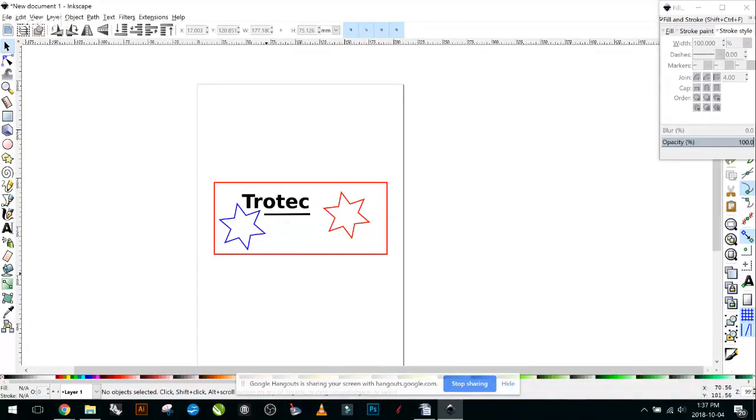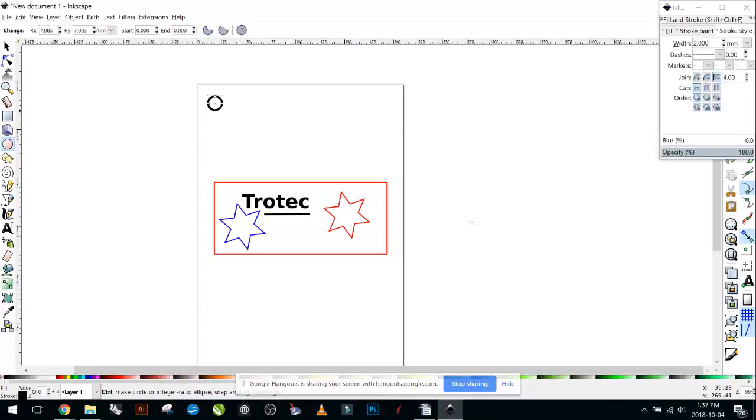But if this was your picture and you wanted your laser to cut out exactly around your picture, for this, it's an easy square. But for our laser to find it, we'll make some registration marks. So we can make a circle here. Hold Control to make sure that your circle is coming out as a circle instead of an ellipse. And in the corner here, we can select inches. You're going to want to select inches, and I'll tell you why in a second.